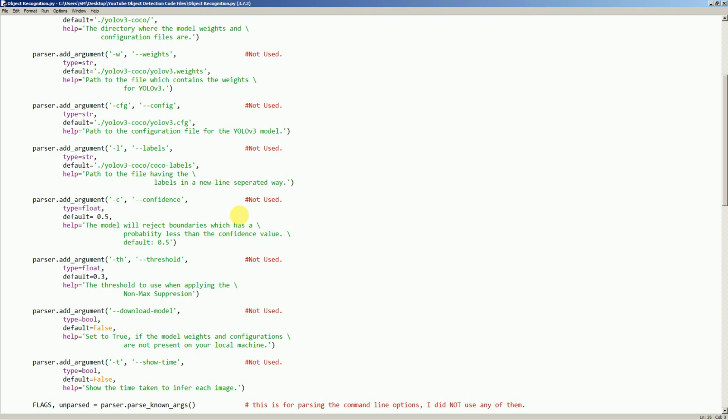That's why I set up the LED flashing light and solid on light. That allowed me to verify that when I sent a character, say ID 41 that I knew was a clock, because it converts the 41 integer into a character and then sends it down the serial port to the Arduino for processing for the EasyVR3, I had to have the Arduino flash codes to verify that, first of all, it got a character, and second, it converted that character from a character 41 to an integer 41.